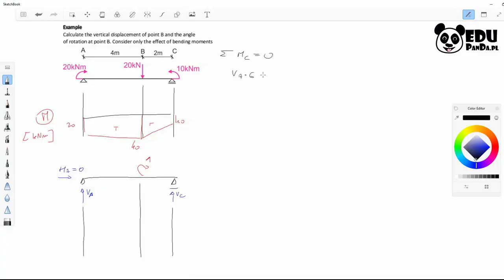On the side note, here again it is indifferent in which direction our unit force will be, whether it will be right or left turning. It doesn't have any significance for us. And now again, to draw the diagram, we need to calculate MB. From the moments at point B, looking from this side, it is simply V times 4. This equals minus 4/6.